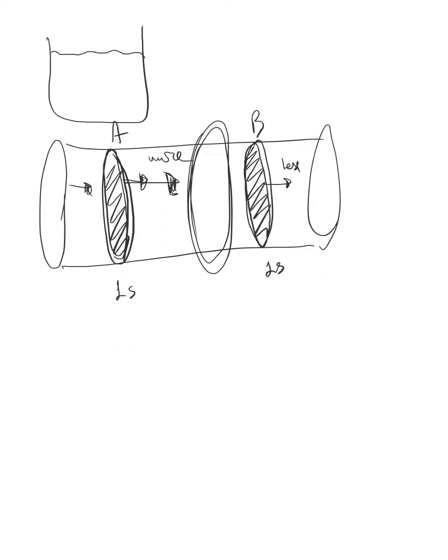And since the pipe is full, the liquid cannot collect there, because that would imply that the liquid is being squeezed and it becomes denser and its volume goes down. Since that's not possible, all the liquid that goes through A in 1 second must also go through B, also in 1 second.